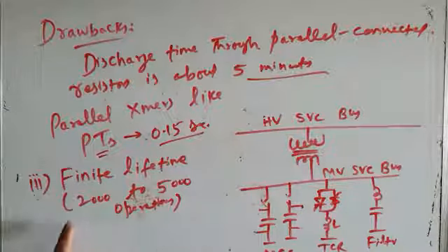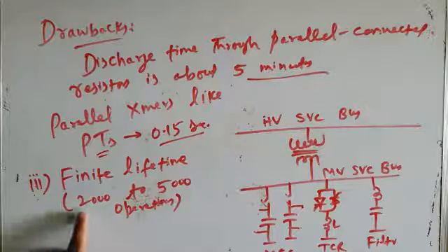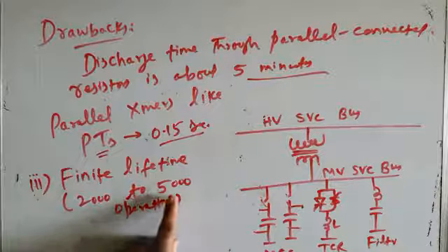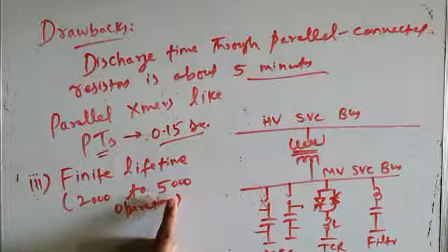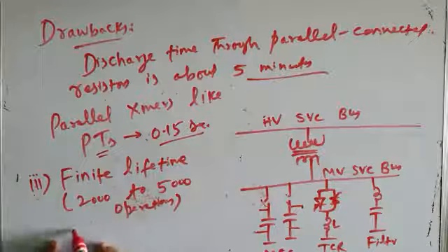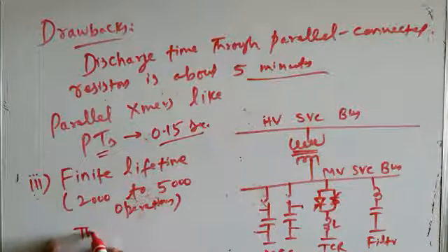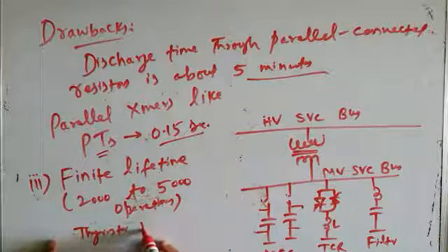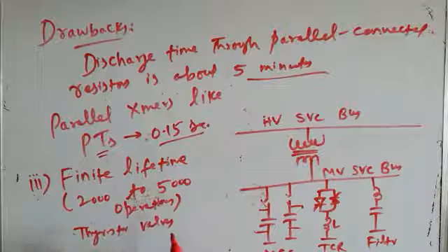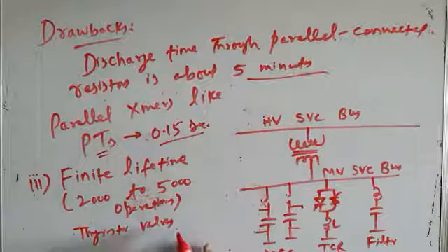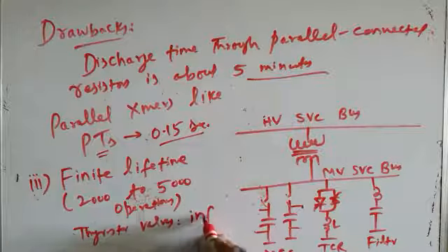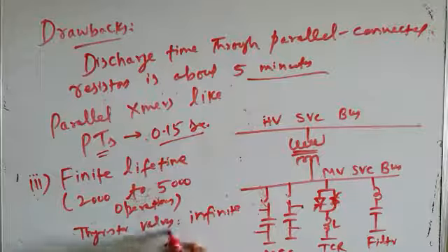And how much lifetime in terms of switching operations? About 2000 to 5000 switching operations only. On the other hand, these thyristor valves, which are used as switches in thyristor switched capacitors, ideally have infinite lifetime.